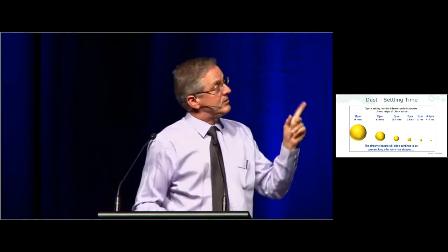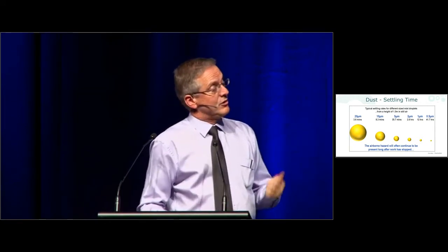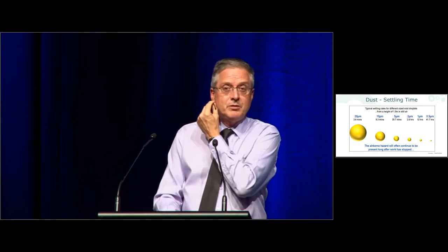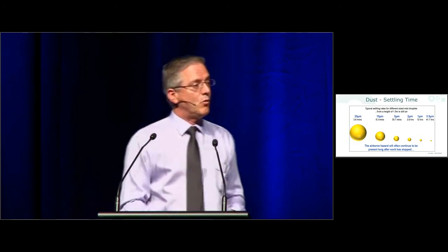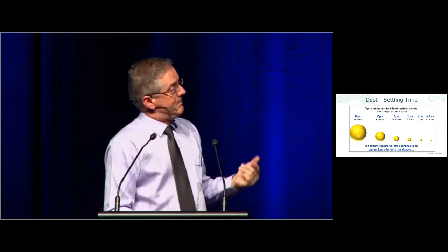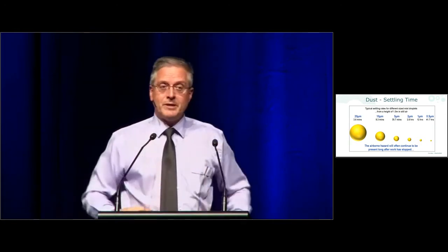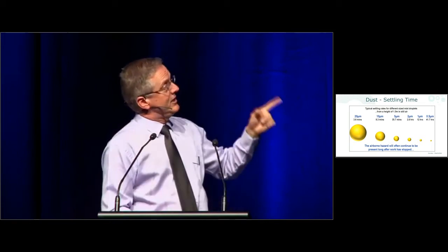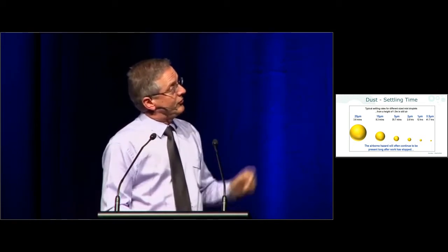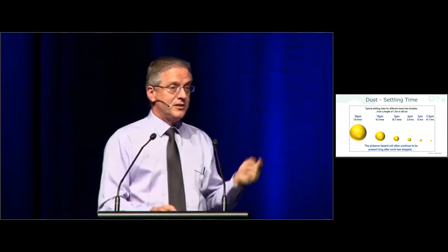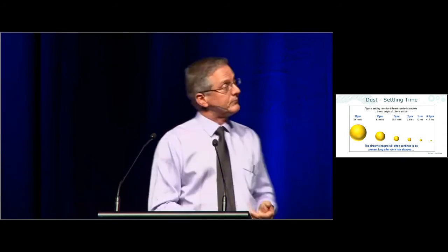This is the one I was talking about that Peter showed earlier on, and what I wanted to focus on here was the small end particle size. When you look at average size for respirable dust, the average particulate size is about 4.25, a little over 4 microns in size. Obviously the smaller dust is, the further it penetrates into your lung. And here we've got the very small particle size down the bottom end that can stay suspended, this is in still air, for days, literally days. And if you've got turbulence, they're going to stay suspended in the air.